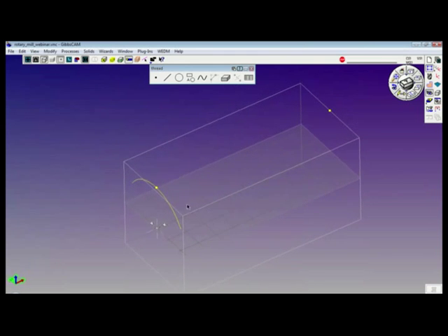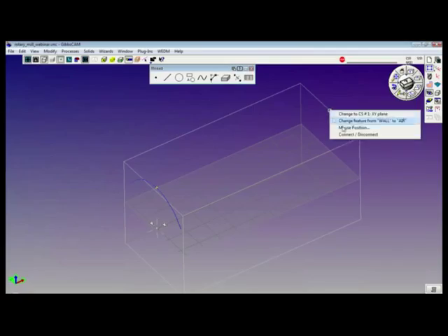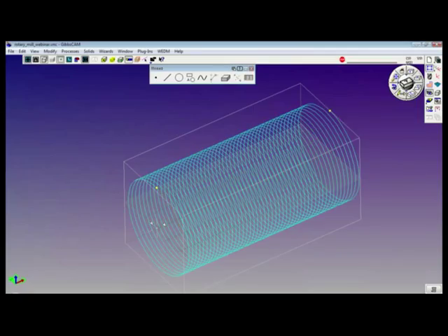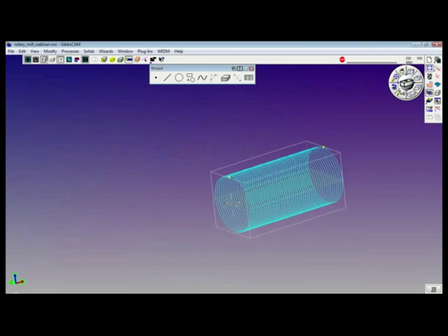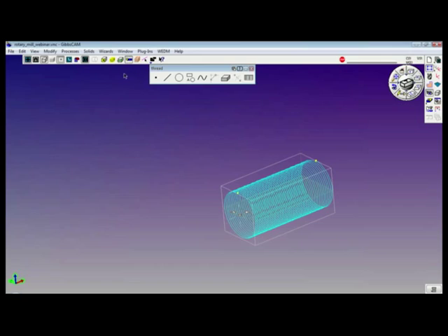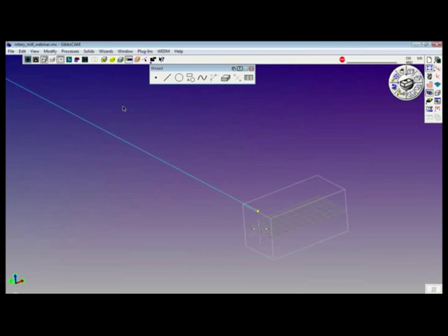The next step is to terminate the line at each point location. Here, connect, select the arc, control click the other point, connect, and watch the result. Look at that. There is our thread in wrap mode. If I unwrap it, it is a straight line, which is, I forget what it was.